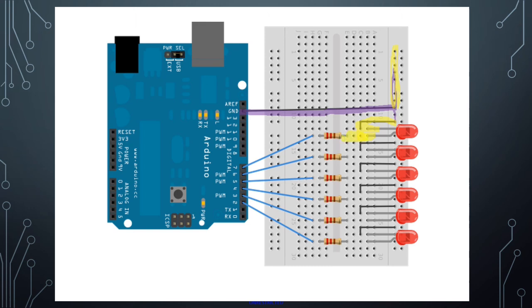So on this side, it's connected to the LED. On the other side, it's connected to a blue wire that leads into a pin. And so this is just duplicated for every single LED. And again, this is where it's nice to run a wire from the ground line to the LED, keep things nice and neat. The LED carries over into the resistor, resistor into a wire, and the wire into a pin. So if you're setting up multiple LEDs, really multiple components of any sort, this is sort of a best practice way to do them. You don't have to set it up this way, but again, as long as you're following the proper rules of a breadboard, really anything works.